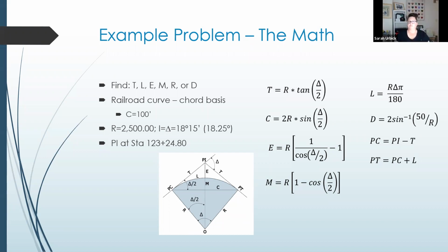So, yep, Mason's on the right path here. 119 plus 23 and a quarter, 23.25. Same process to get the other end. So what we did on that first example, where we were looking at the fish hook and we went 300 feet, right? We started out with the two endpoints and took the difference.